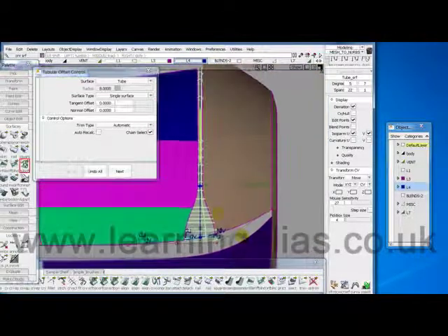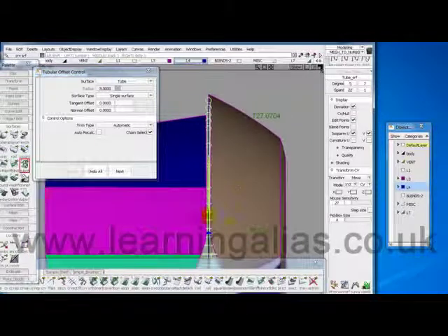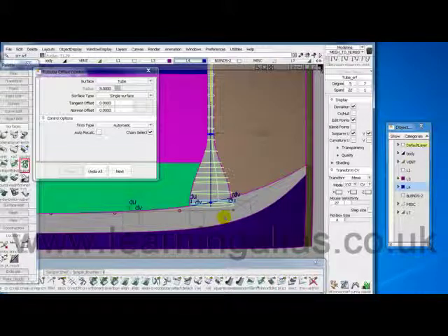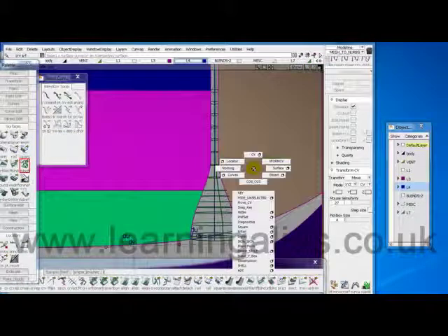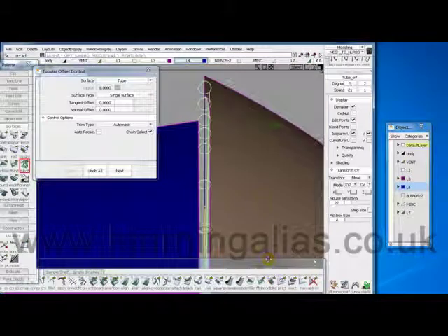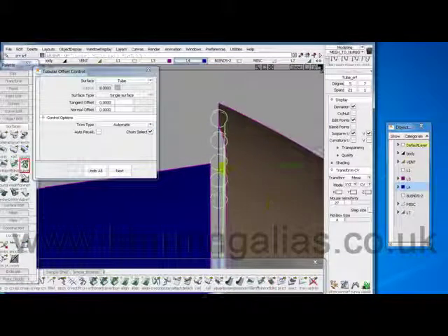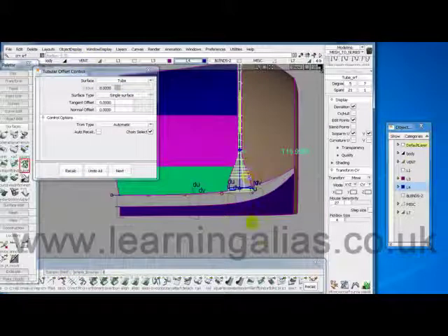Let's have a look. So by sliding that down there, it duplicated it, and manipulating it anchored that width for us there. Okay, we'd have to measure that width, and this is the shape of the blend that I want. So now I'm going to pick nothing, and I'm going to delete this locator here. So okay, I'm going to type in here radius equals 8.7, and recalc, and that should have sorted out the problem for us. I'm just going to hit enter and hit recalc. Now we can delete the tube.